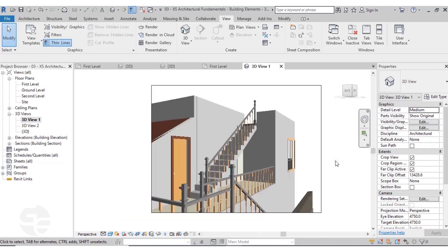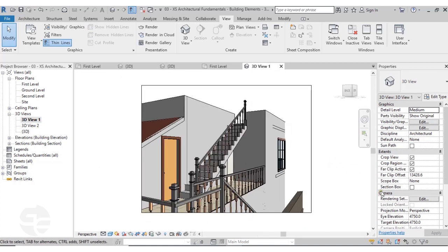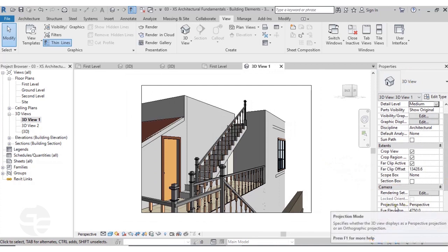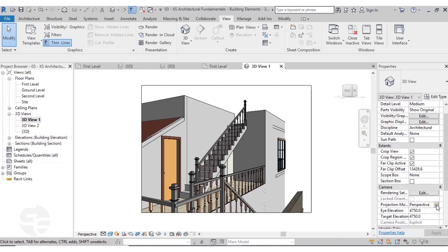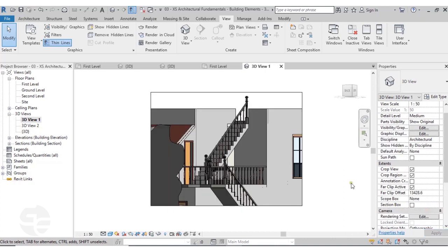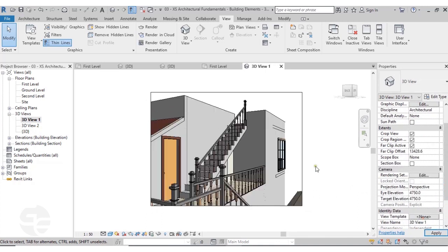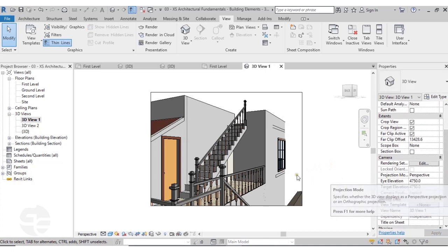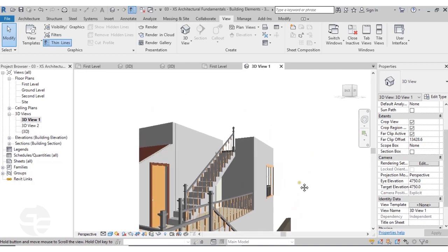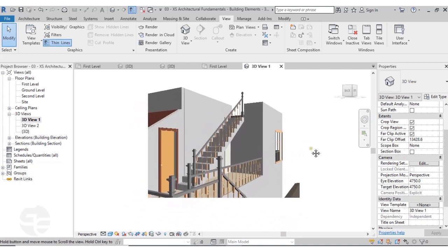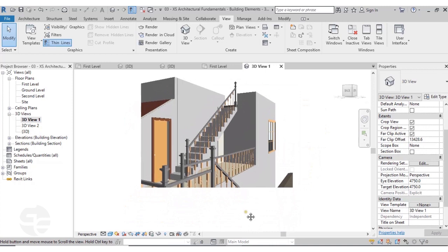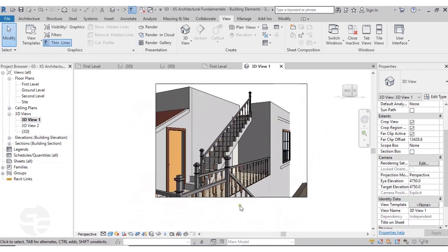Now, the very first thing that we can see is I can simply go to the Properties panel here and change my projection mode from perspective to orthographic, and again from orthographic to perspective, easily using this option known as the projection mode. Further, if I want to pan this particular view or orbit the view, the picture frame is panned or the picture frame is orbited and not our 3D or camera view given here.